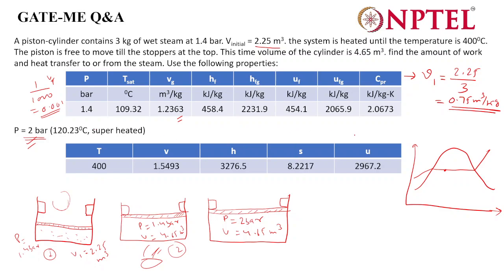Okay, that I will see. But that assumption you got, na? What I'm saying? Why are we neglecting this Vf? So anyone found what the dryness fraction is here? Yes, 0.607. Anyone confirm? Okay. So now we have the value of the dryness fraction.